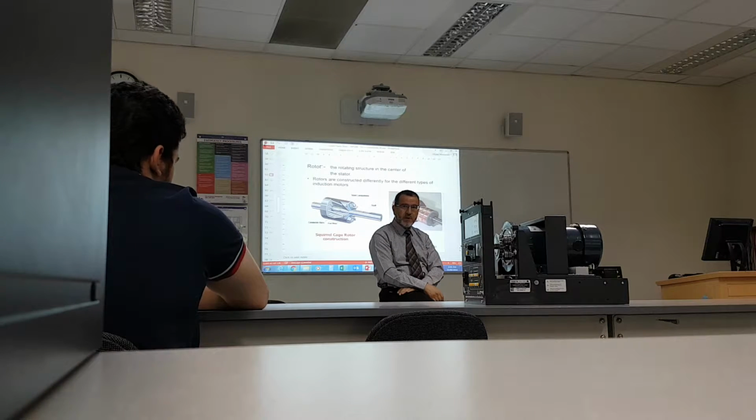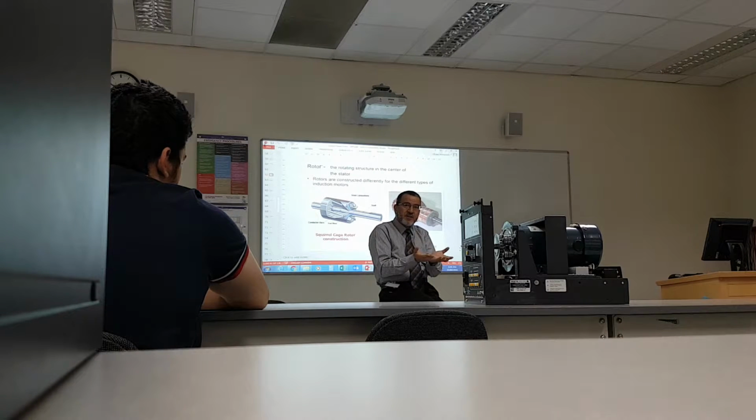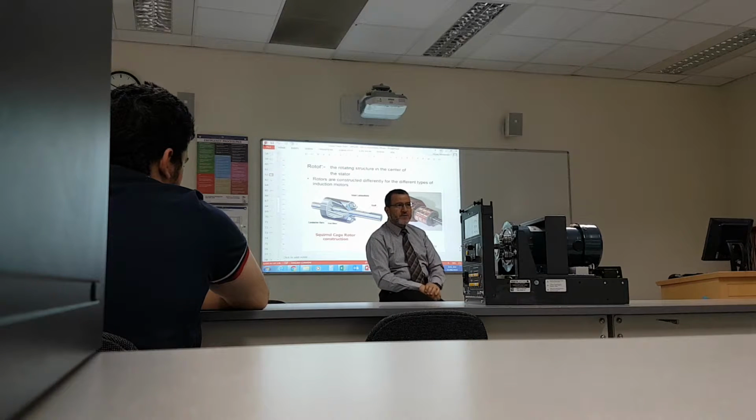Right? If it is normally excited, it's neither consuming nor producing reactive power. If it is underexcited, it's like an inductive load. That means it also requires reactive power in addition to the real power, because it needs to make up the difference. Underexcited means what? There's not enough magnetic flux in the rotor to provide a sufficient amount of magnetism to pull in the poles. So it borrows more from the reactive side.